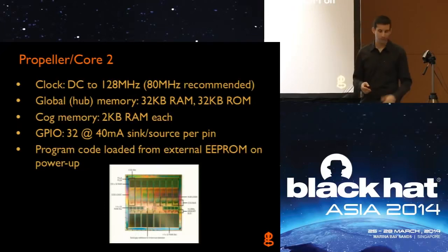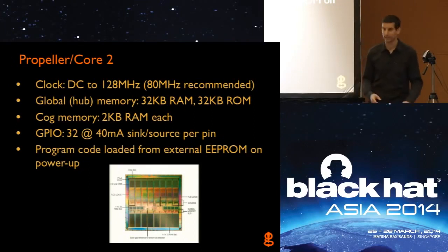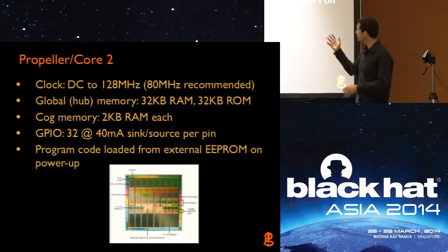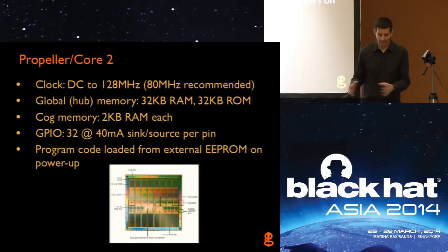But 32 pins, we're using 24 of those pins for I/O, and the other stuff we're using for the analog to digital or digital analog converter and stuff. So it's a pretty good number. You could always design a similar JTAGulator with an FPGA with 128 pins or something. So you could potentially get larger I/O, but I think 24 is sort of a good number for now anyway.